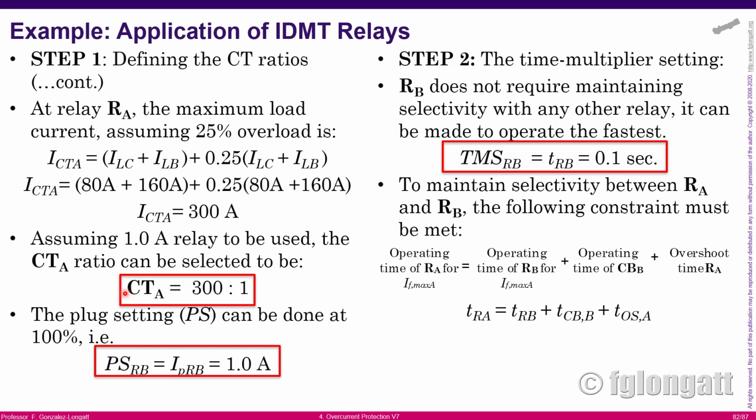In this example, it's a very academic example. In this case, both current transformers are matching standardized values for currents, okay? If your calculations give you a number that is not matching a standardized value, you must go and use the immediately above level of the standardized values, okay?